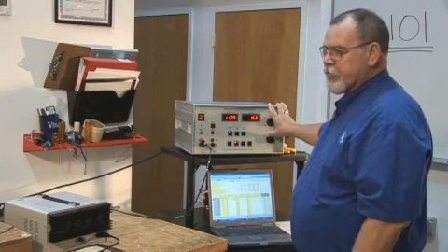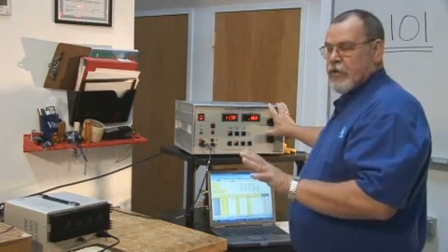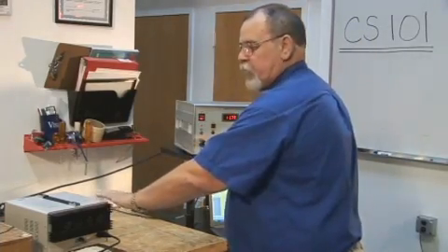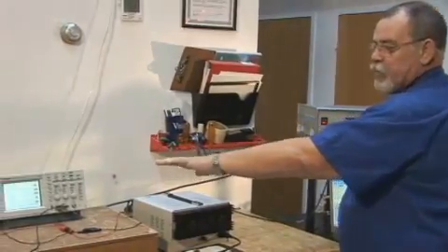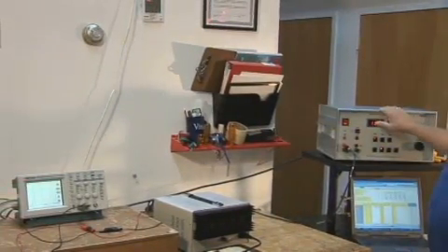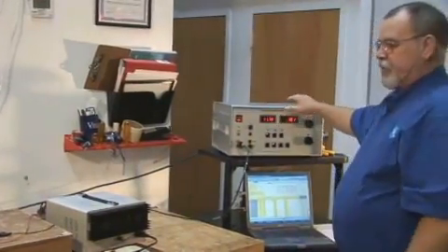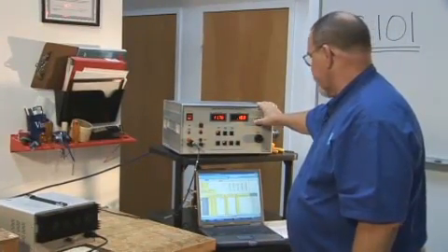I continue to sweep the frequency, monitoring 3 things. So your eye is constantly going between things. Is the test article performing correctly? Do I have my peak-to-peak voltage that I should be going, my test level, and am I not exceeding the forward power calibration in that voltmeter? So we're constantly monitoring all these activities. It's great if you have a partner monitoring the test article for you.